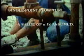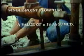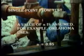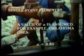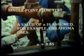It should be recognized that only a single rate flow test is needed in order to obtain the back pressure flow equation if the value for N is assumed as known. This is the case, for example, for the single point test allowed by the Oklahoma Corporation Commission. In that particular situation, the Commission allows the operator to assume a value for N of 0.85.